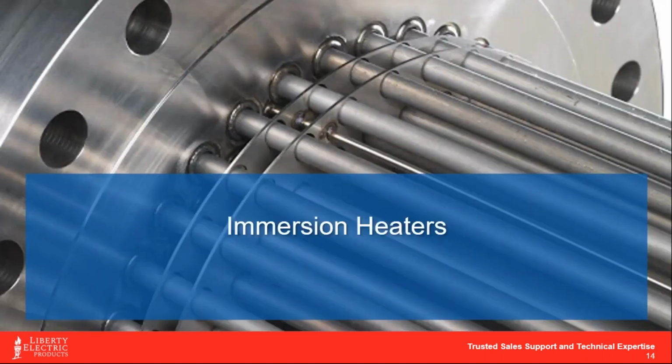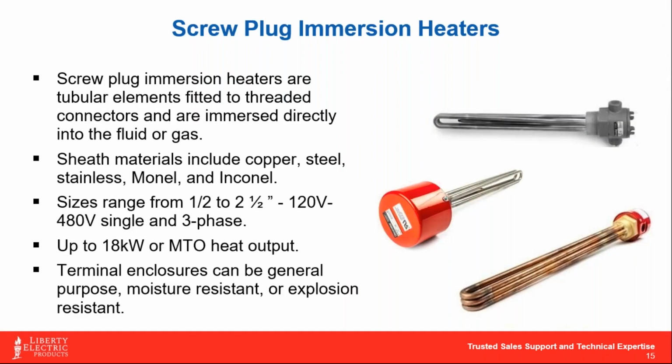Immersion heaters. Immersion heaters are really common, and probably the most noticeable one that we see a lot is screw plug immersion heaters. These are the smallest in your immersion heater family, and these are connected to whatever appliance or device they're going into with a threaded NPT connection. So they just literally screw right in, and you wire them up and away you go.